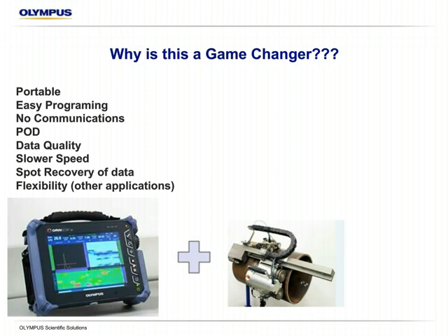This is the same system you can be using for weld inspection, looking for cracking, or component testing, and there's really no distinction. It's not a dedicated corrosion mapping system. It's a full flexible phased array for all different types of ultrasonic applications.